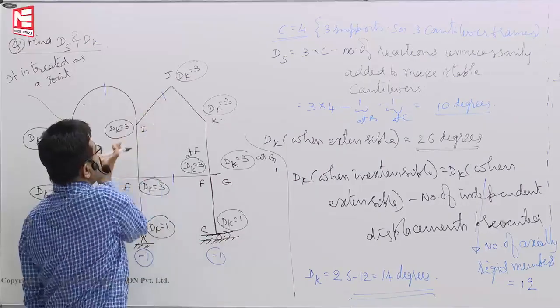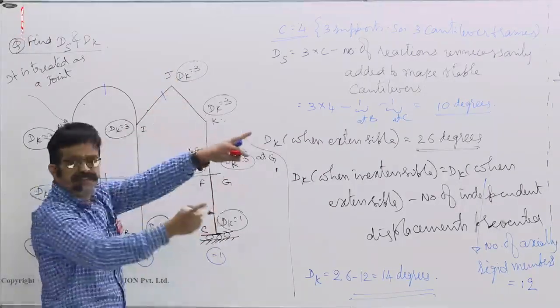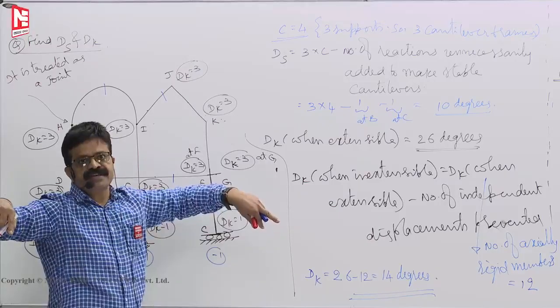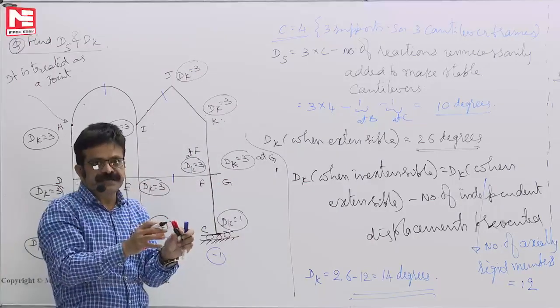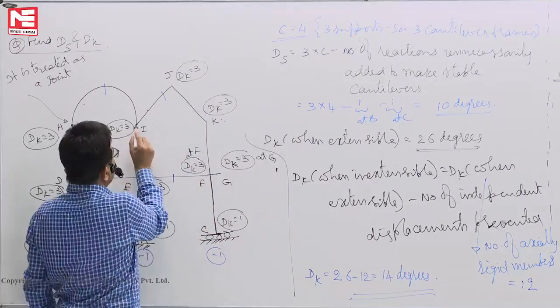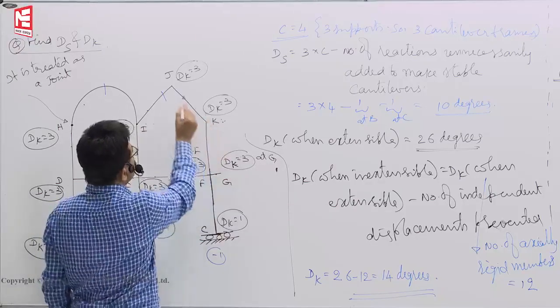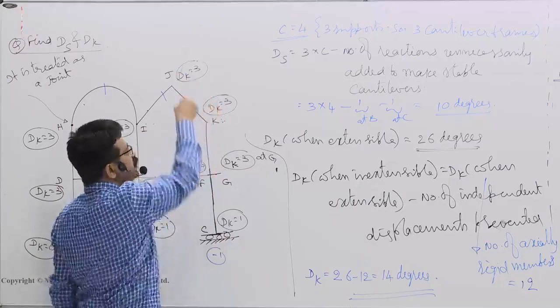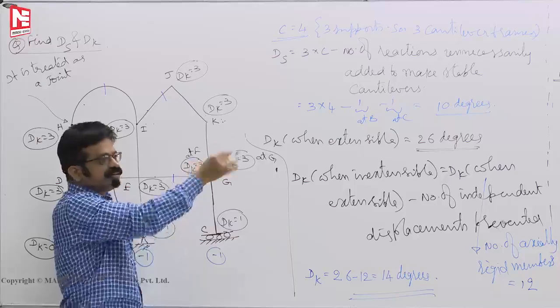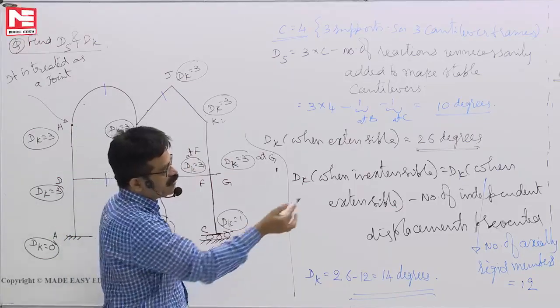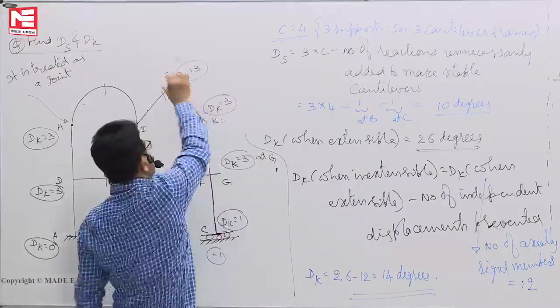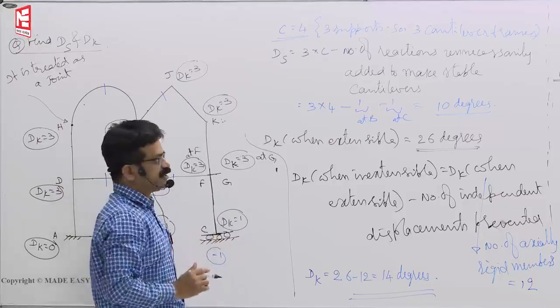Similarly, the triangles we can form, as I told you earlier, inclined members, trigonometric relationship I have obtained. So if I know how much this moved, how much this moved, I can predict how much this moved horizontally, how much this moved vertically. We can find them. They are known quantities, but rotation is independent, theta j.